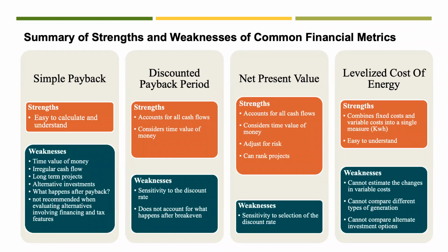It is difficult, though. You can't necessarily use levelized cost of energy to compare across different types of generation, because there's value in the fact that wind and solar are emission-free and renewable energy sources. However, on the other side of that, there's value to natural gas, coal, and nuclear in that it's a base load source that you can control, and you can ramp it up or slow it down as you need it. And so it's difficult to compare different technologies using the levelized cost of energy.